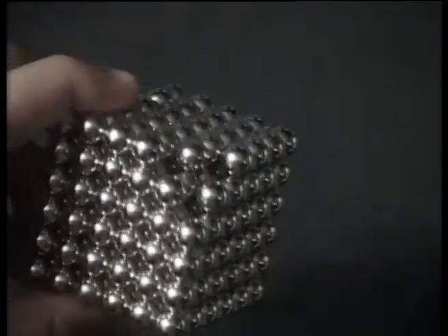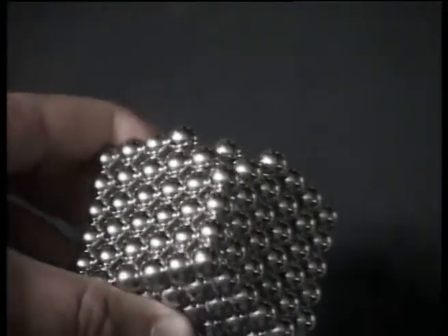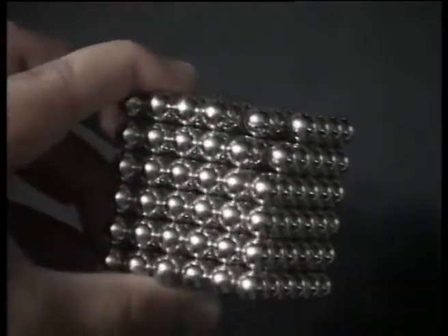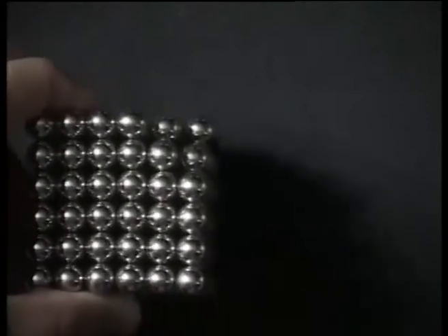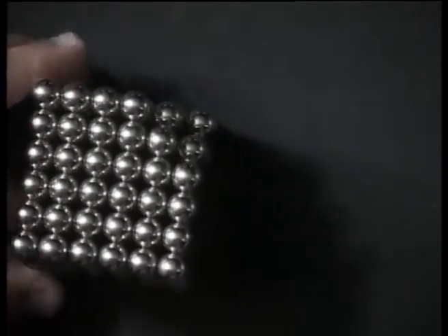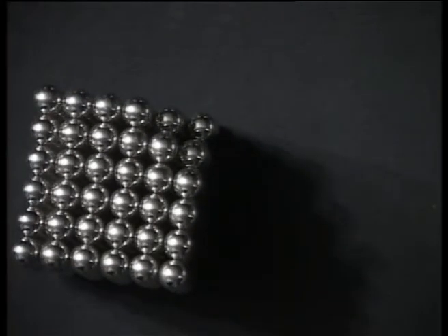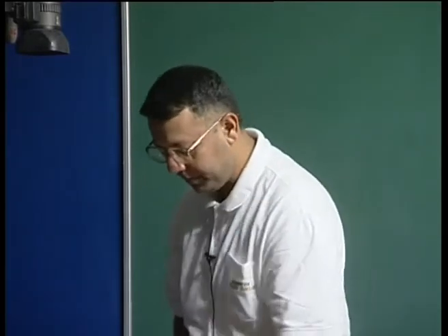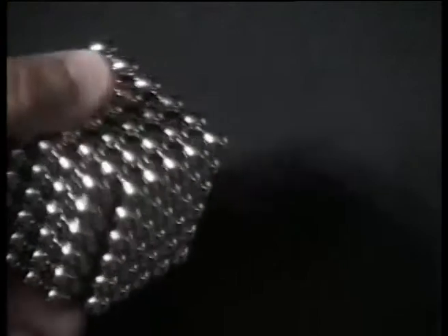So these are my 111 surface atoms, and you can see that this 111 surface is more loosely packed in the simple cubic crystal as compared to the 100 surface. While in the case of face-centered cubic crystals, we have already made the calculation that the 111 surface is the close packed surface and there is a higher density as compared to the 100 surface.